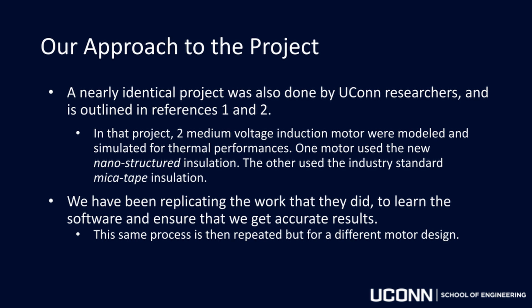Our approach to the project: a nearly identical project was done by Yukon researchers. In that project, two medium voltage induction motors were modeled and simulated for thermal performance. One motor used the new nanostructured insulation and the other used the industry standard mica tape insulation. We have been replicating the work that they did to learn the software and ensure that we get accurate results.